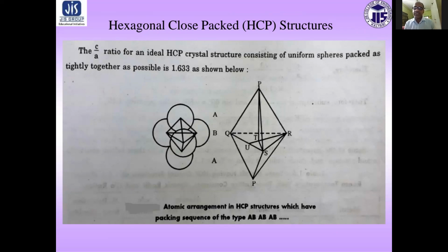As we can see, there are 3 interior atoms at plane B, and the corner atoms present at the top and bottom planes, which are denoted as plane A. Now we need to understand this geometry: the 3 interior atoms touch each other, with their centers being Q, R and S respectively.